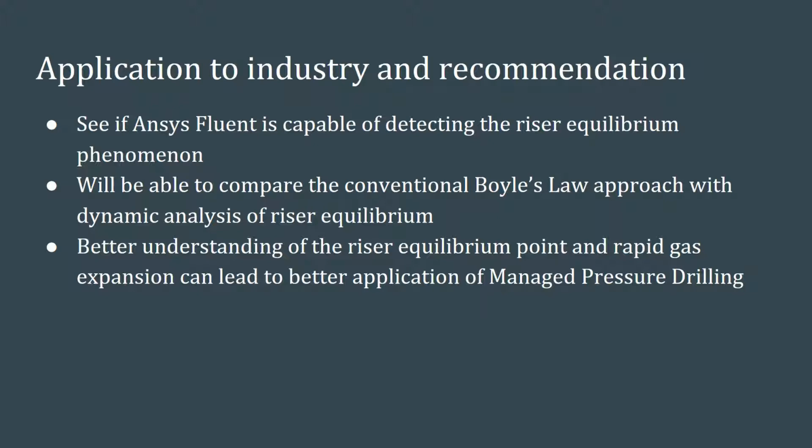If we are able to provide a more precise determination of this column, we will be able to find a reduced collapse pressure for our system. This better understanding of the gas expansion process in the riser could hopefully lead to better applications of managed pressure drilling in the future. MPD can be utilized to provide a back pressure which can reduce the rate of gas expansion and can prevent severe unloading events.